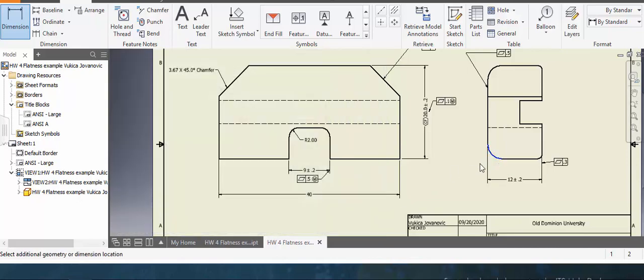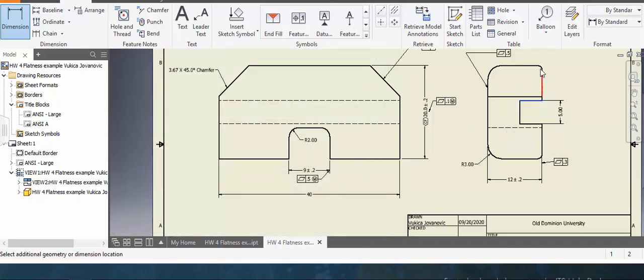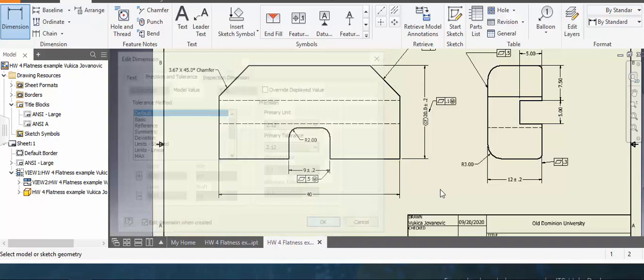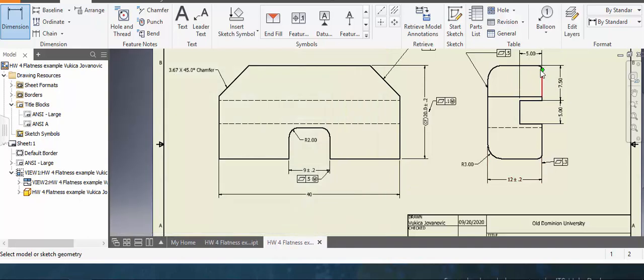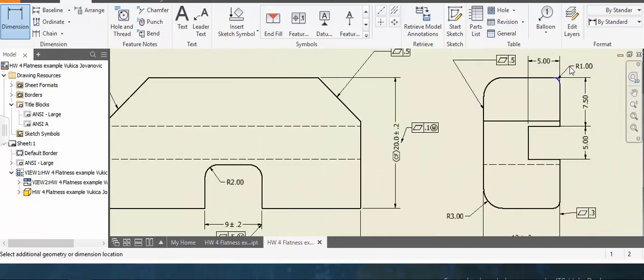and we can also have it in two other places. I think there was one more radius I didn't put, but you can add it, so you will have 4 different ones. Now I'm dimensioning the hole, so there are 2 dimensions of a size, and also for location we have to make sure that this is location. We can go from the upper horizontal or lower, and then for this chamfer, zoom in, because you can't do it so easily there.